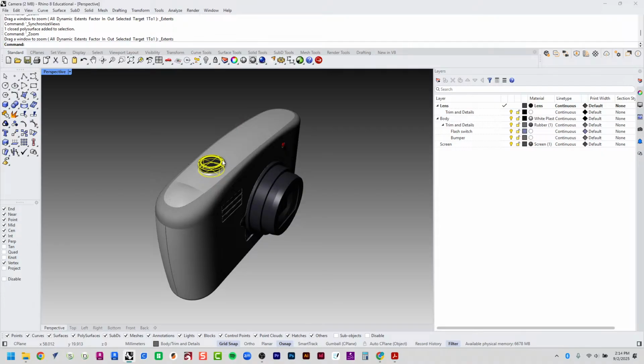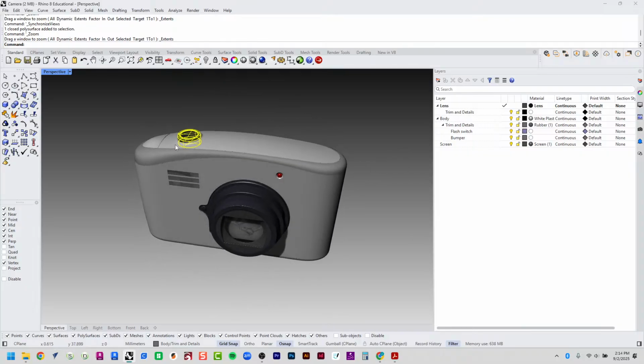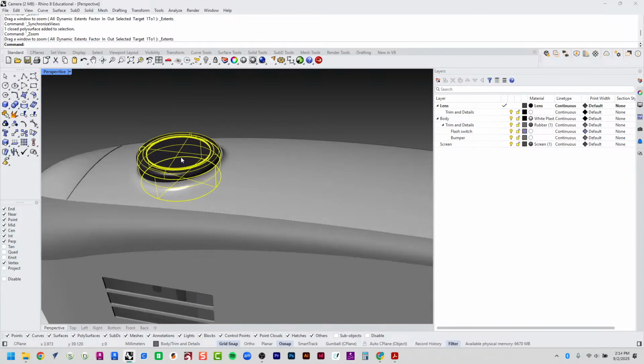Okay. And what that does is when I say zoom to full extent on that piece of geometry in this view, when I go to orbit or zoom in and out, my camera is now locked on to this shutter button. Okay. That's going to be really handy for you all when you're 3D modeling.